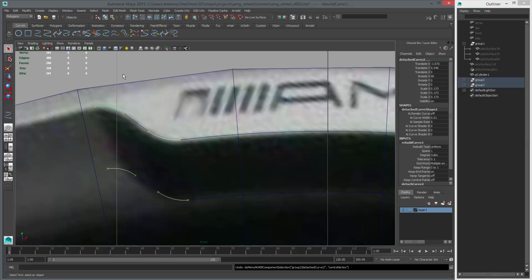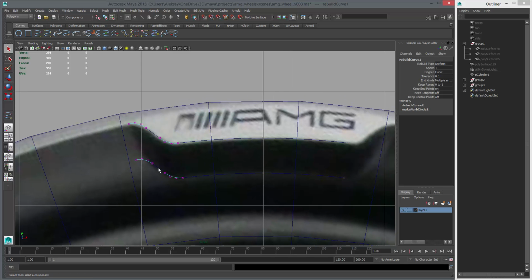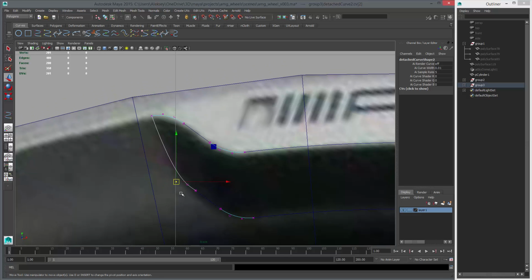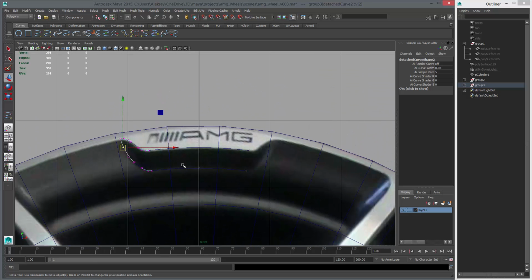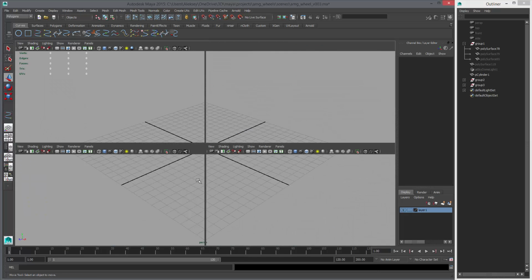We can also check their direction to make sure the direction is the same. And that's the U and the square. That means that's the direction, so this curve's direction is this way, and that one is this way. So that's perfectly fine. Now I'm going to select this point and snap it there, and just spread these out. There. So I'm going to unhide this piece.